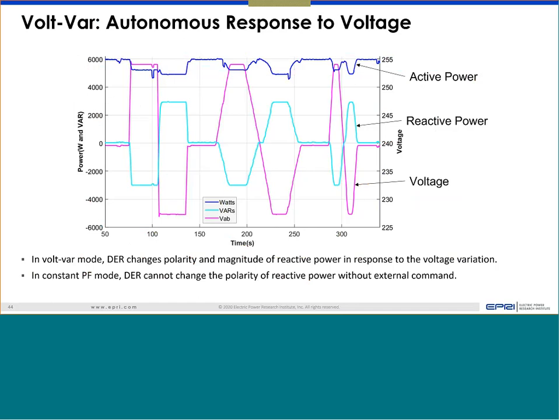So this is a 6 kilowatt inverter. When there is no VAR, you can see it is generating 6 kilowatt. The moment we ask for 3 kVAr, absorption or injection, you can see the power has to be reduced to generate that much reactive power. So from 6 kilowatt, it most probably dropped to 4.8. So almost 1.2 kilowatt of real power was reduced whenever there was excessive reactive power demand. When the reactive power goes to 0, the power goes back.